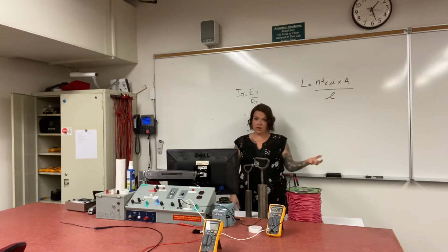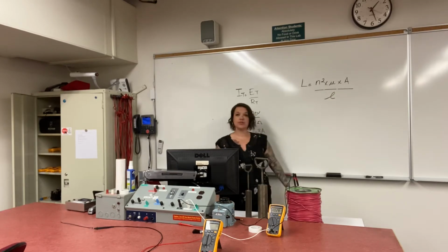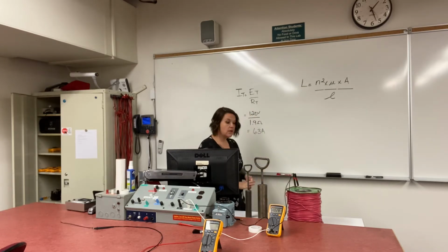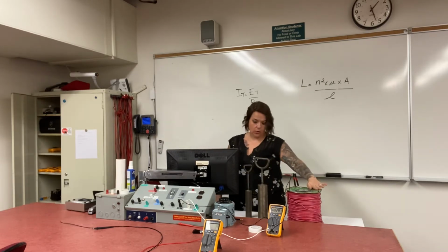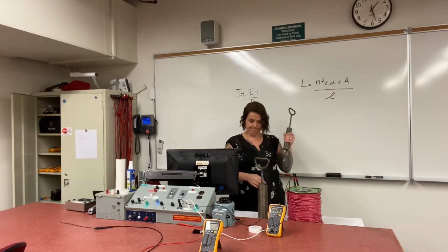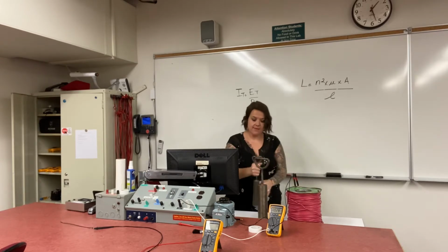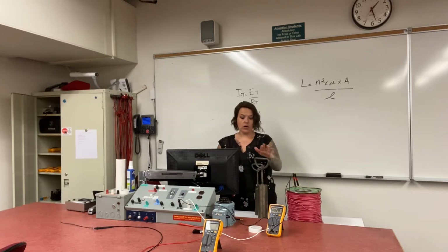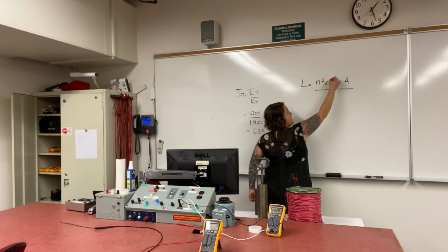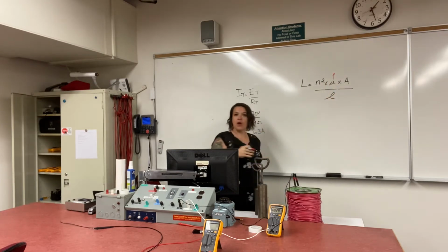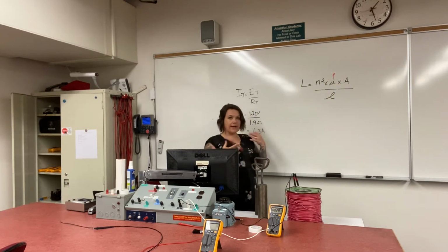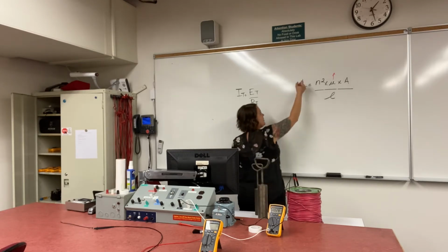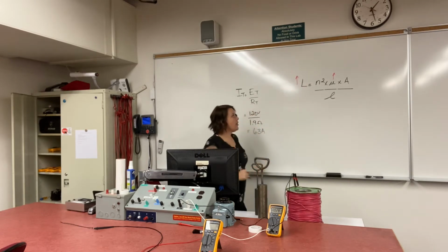Area of the core is also directly proportional to the amount of inductance that's being produced in our coil of wire here. So I'm going to go from an air core to an iron core, okay? And we're going to see how that affects the current. If I am replacing the air core with an iron core, I am increasing the permeability of the coil, and directly proportional as it is laid out mathematically in our formula, we would expect an increase in our inductance.